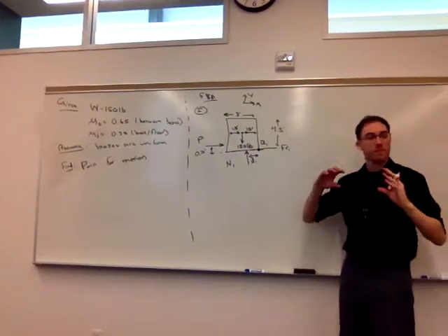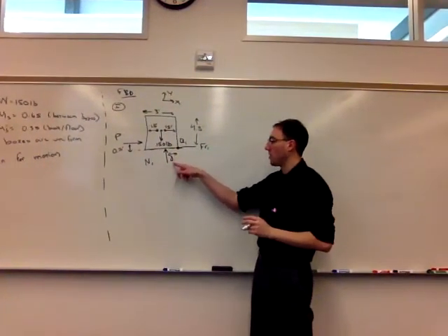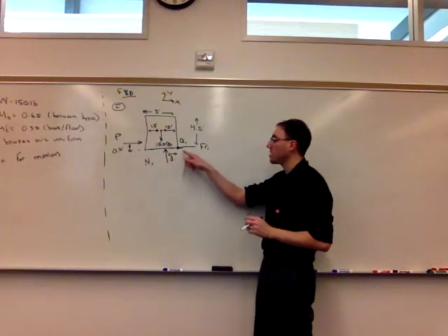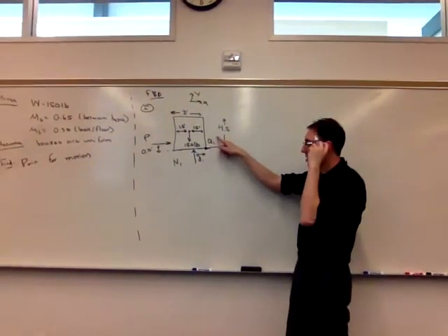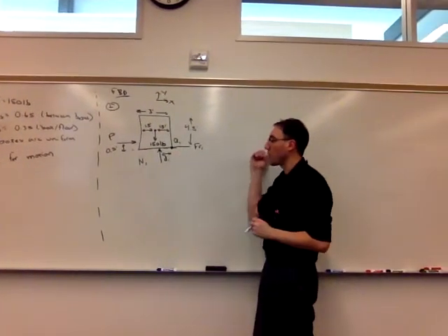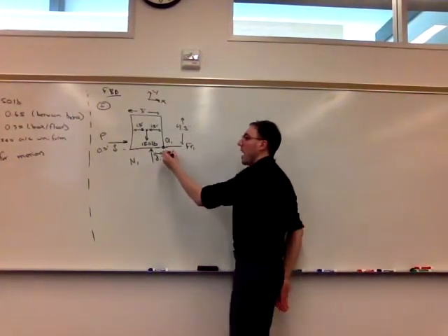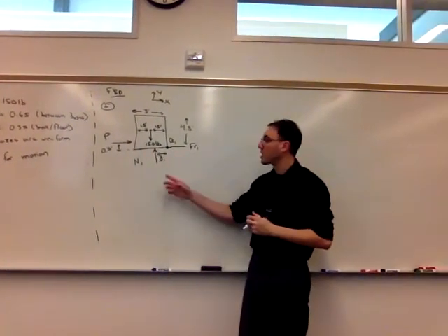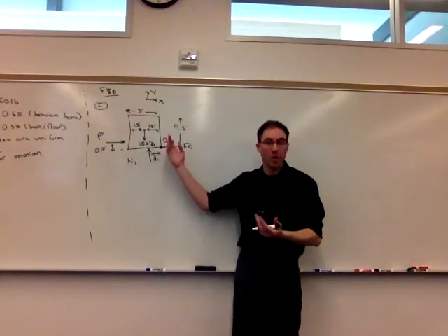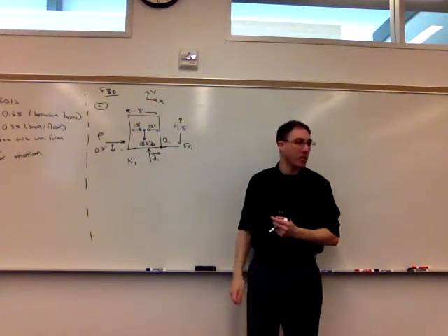So I put the equivalent point load at the equivalent location, neither of which I know at the moment. And I choose to measure this from the right corner, which I'll call Q1. We'll see in the equations why I did this. I'm measuring it from the right-hand side because that's where I think this would tip. I could measure it from the left-hand side also. This is just going to be a little bit easier in my equations.